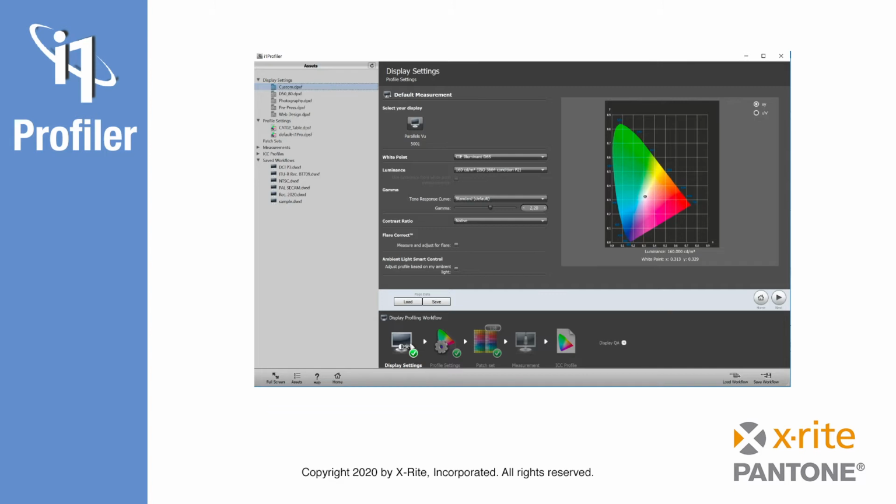LCD displays have a native white point between 6500K and 7500K, and the vast majority of LCD panels have a manufacturer's specification of 6500K. Therefore, 6500K is the recommended white point for most situations. Gamma refers to the behavior of tonality between black and white for a color space or device. We need to apply a tone response curve because our eyes respond to relative rather than absolute differences in brightness. The current industry standard is to set gamma at 2.2.